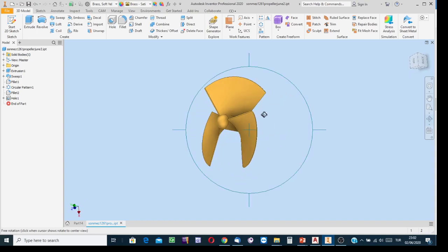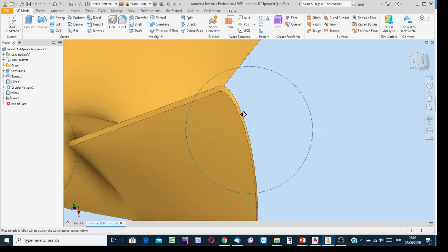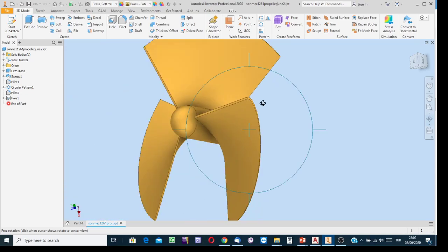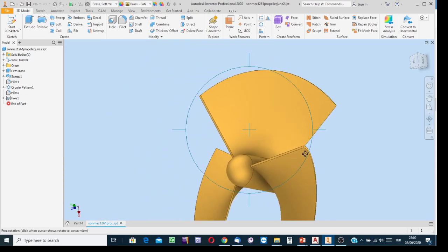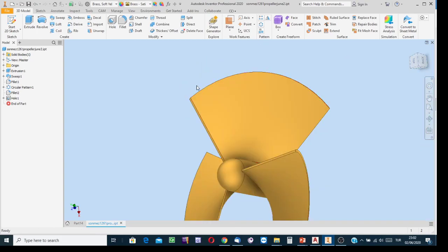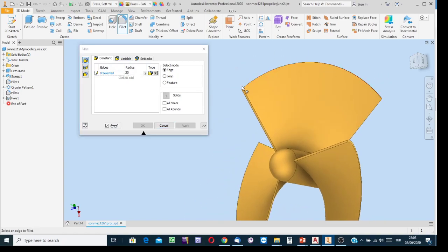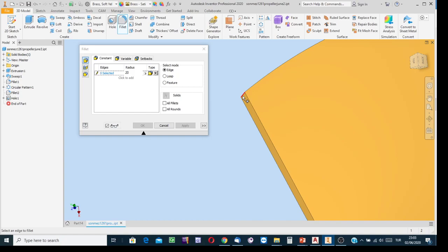Although I used the array copy process and indicated the already created blade with the recommended roundings, the array copy process considered the initial form of the blade. So you see, the roundings could not be had at the edges of the created copies. Unfortunately I need to apply the rounding process one more time for rounding the edges of the created copies.